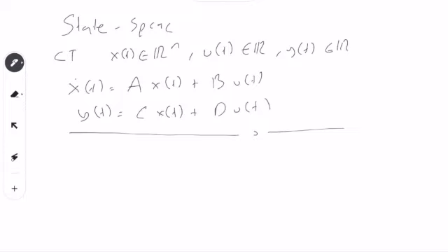Okay, so in order to make it time varying, we do a simple trick such that instead of A, B, C, D being constant, they now become time varying quantities. So let's clean that. A of t, B of t, C of t, and D of t. Now it is a linear time varying system. By just making the A, B, and C matrices depend on time, at least one of them, we make the system linear time varying. Okay, good. So what about nonlinear?